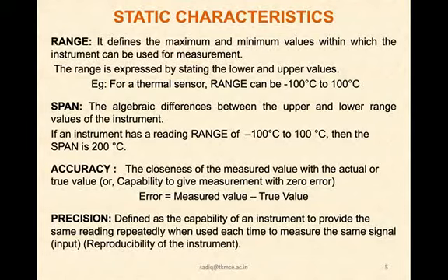But if your requirement is to measure the temperature during a machining process, where the temperature can go up to even 800 degrees Celsius, the thermometer will not work. There the range is different. You will have to go for a different device called a thermocouple or some other device. If it is a heat treatment furnace where a thermocouple may not work, in certain cases you may go for a thermopile.